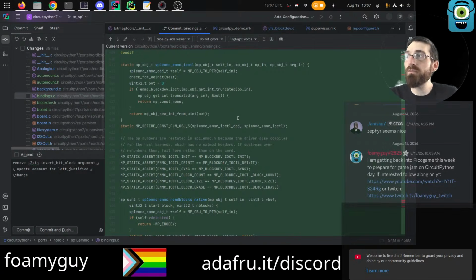At a high level, one is the way the watchdog works. The watchdog gets armed by the bootloader, and CircuitPython, or whatever app comes after the bootloader, is responsible for feeding the watchdog. Otherwise, the device will reset. So there's new code in the core that will feed the watchdog at appropriate times when other stuff is occurring, so that it won't just reset during a file write or a while true loop and that kind of stuff. So that's one of the things, the watchdog.